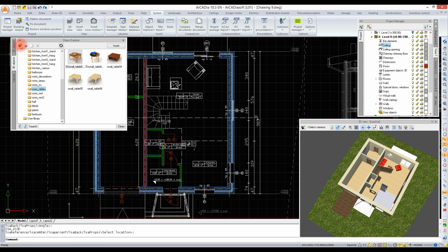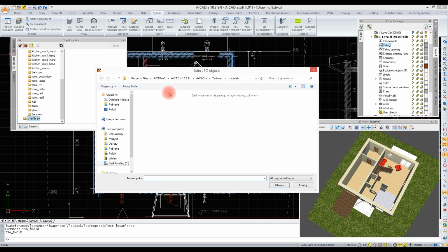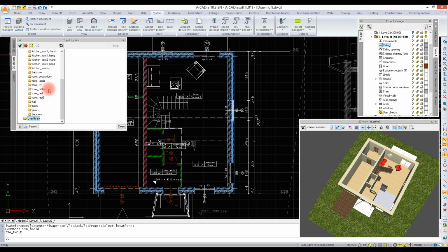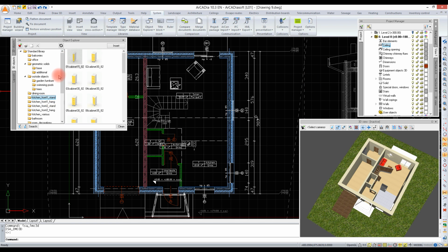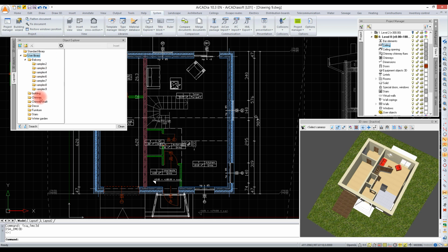Three-dimensional objects can be imported into the program using 3ds, ACO, and O2C files, thus expanding your own library. You can also save your own objects, for example created in the option Solids or Create Groups of Elements, that you can use in each subsequent project. These can be, for example, furniture sets that we can use in subsequent projects. We enter such systems analogously to individual 3D elements.